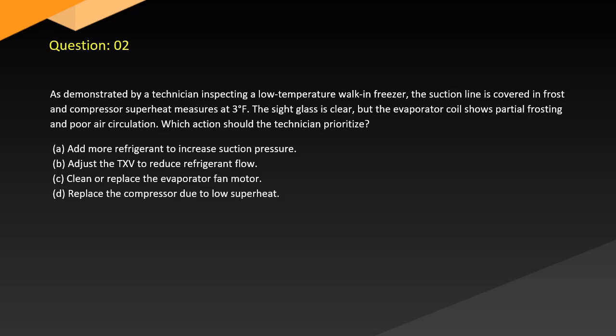A. Add more refrigerant to increase suction pressure. B. Adjust the TXV to reduce refrigerant flow. C. Clean or replace the evaporator fan motor. D. Replace the compressor due to low superheat.